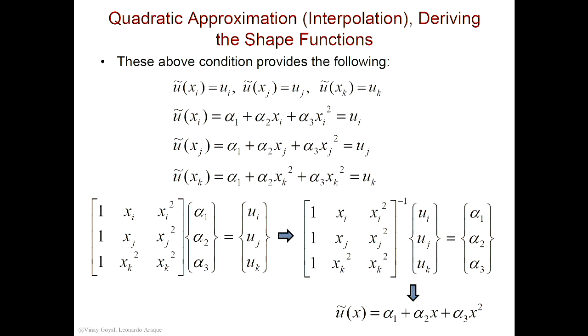And then the second step is to define the element connectivity, star element, and then you have the element connectivity at the bottom, right? So the element tells you what nodes go with the element, and those nodes have coordinates, right? That's how I know what's xi, xj, and xk. That's how I know this, okay?